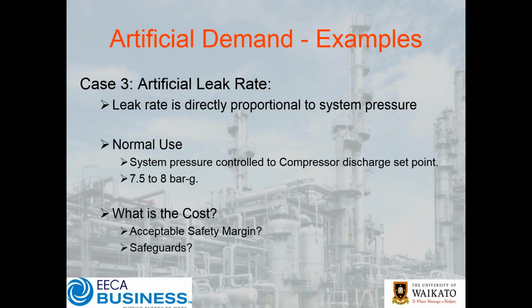So obviously, receivers can get expensive. It's not uncommon for a decent sized receiver to be sort of in the vicinity of $20,000 or $30,000. And so obviously they can get expensive to install, and so when you're trying to trim a capital budget, they're an easy thing to eliminate. They're a big target and they make a big difference. And so when you cut those out, you think, well, let's just add another half bar at the compressor and we should be all right.